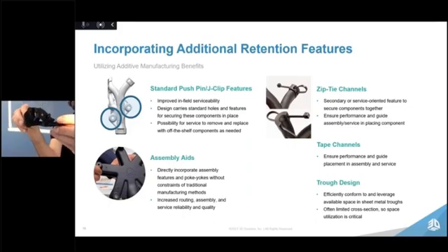Within this part, there are standard fitment accommodations, so a hole here and some other bosses and holes within the part, and those can accommodate things such as push pins or rivets or spring clips, or fir tree fasteners can be housed, for example, and that gives you the ability also to create standoffs and fitting guides.